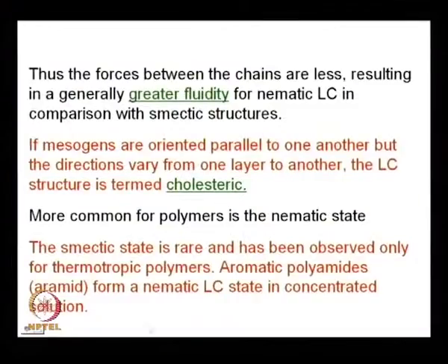More common for polymers is the nematic one. The smectic state is rare and has been observed only for thermotropic polymers by melting only. Aromatic polyamides, as I showed there, or polyimides. Aromatic polyamide means aramid, it is a Kevlar fiber, which is used for making bulletproof jackets. That means it has the capability of absorbing huge impact without failure. That property comes from their molecular alignment.